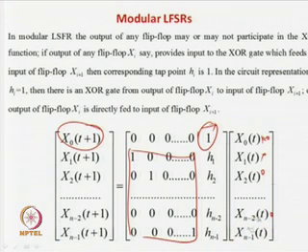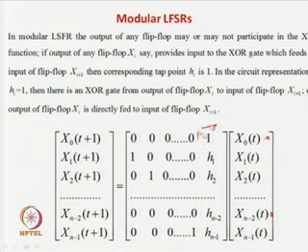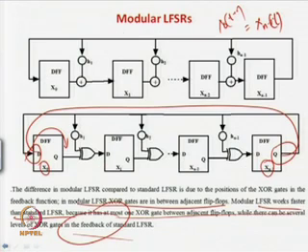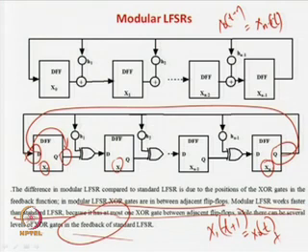Okay. Now next we can see how you can develop the expression for x1 t plus 1. So, if you see x1 t plus 1, what is this? The x1 t plus 1 will depend on this one. So, it will obviously be depending on x naught t. There can be an XOR. If H1 is 0, then there is a direct connection, then x1 t plus 1 is equal to x naught t.